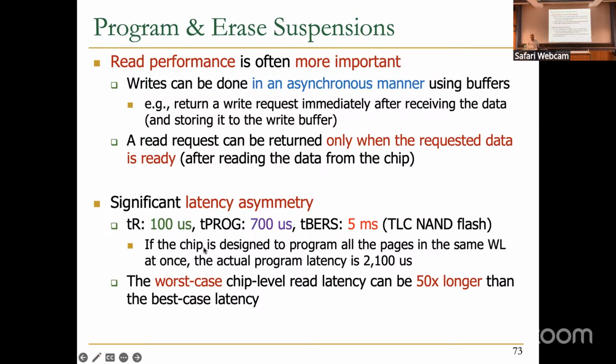So now you can see that if the chip is designed to program all the pages in the same word line at once, meaning that this SSD is TLC, right? It is a TLC NAND flash. If you want to program all 3 pages at the same time, which is usually like that, you need to spend 2100 microseconds to program all these pages.